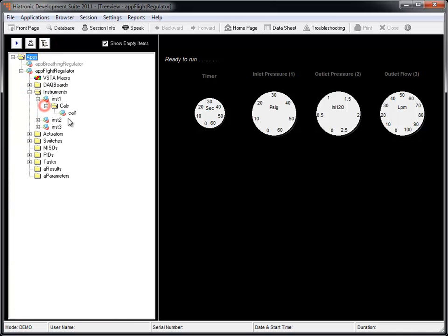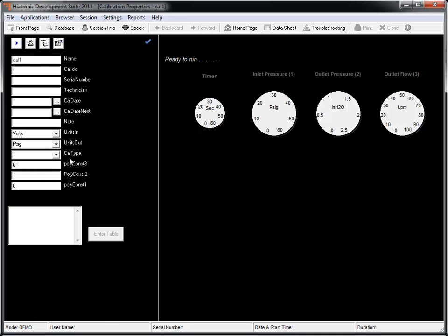So if you go into calibration 1, as I mentioned in a previous exercise, we're just using a simple polynomial fit. But more typically, you're going to change that to 0, and you're going to put voltage. 0.1 volts equates to 0.3 engineering units, and then you'd put 5 volts equates to 50.2 or 0.3 engineering units.